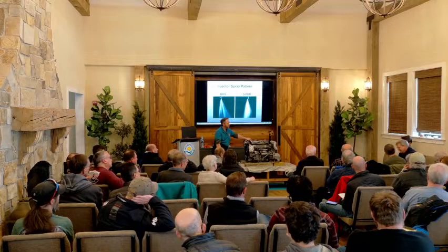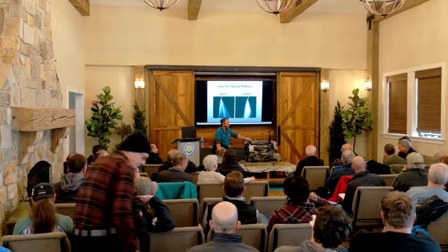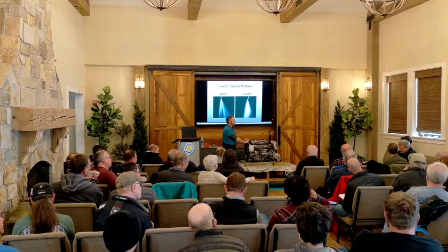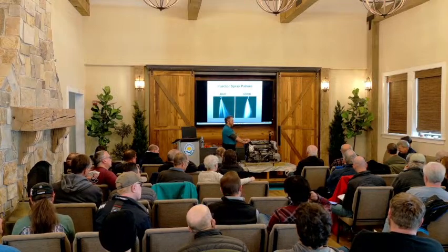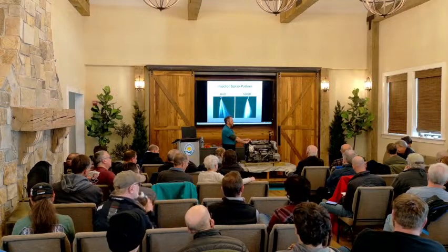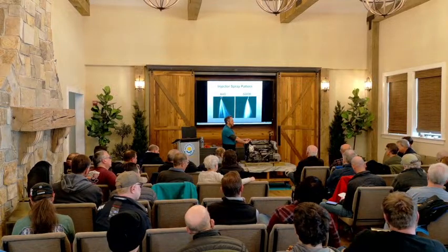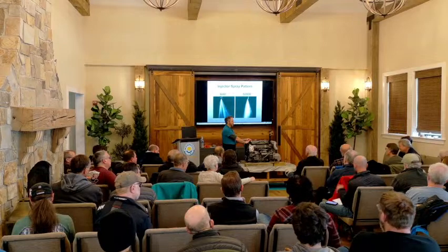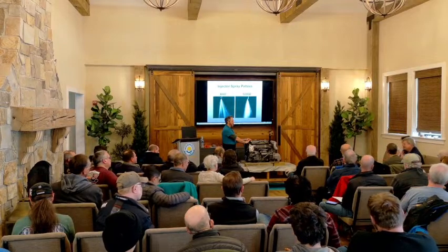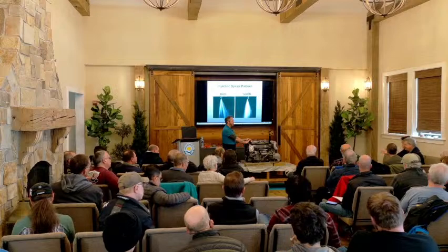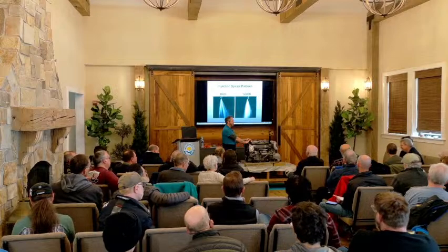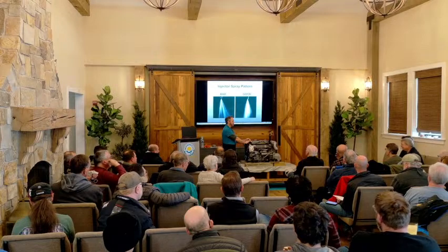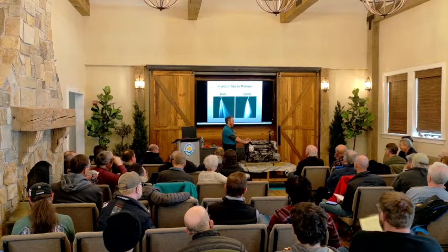So I have a large sailboat with an 80 horsepower Westerbeke diesel. I've read and heard from lots of diesel sources and looked at power curves that diesels are the most happy running at 80%. Max RPM is 3,400, mine's 2,800. My diesel actually seems to me to be much happier running at like 2,400 instead of 2,800, and it's only like half a knot less. It seems happier, it uses half as much fuel. Do you have thoughts on that 80%?